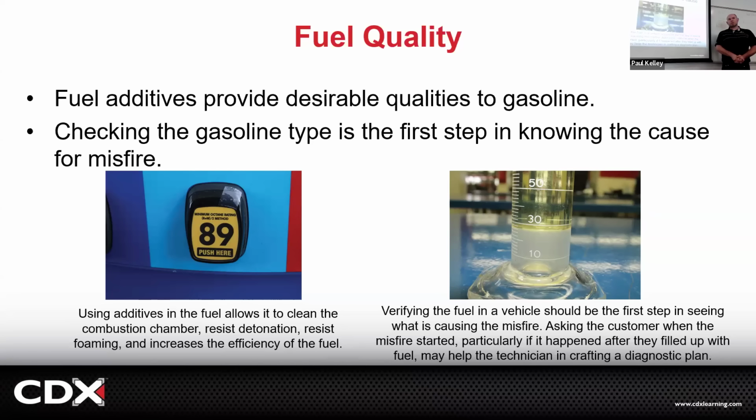I've seen it go for 6 months. I've even seen it approach a year. Anything after a year, that thing's gonna be messed up. So if you put fuel in something, a dirt bike, I've had this too many times, you don't use it for a year, and then you're like, "Oh, I finally got a day off, let me go start my bike." I got to clean the carburetor again. It just doesn't last that long. Fuel does not last that long. It's perishable. It expires. Okay, so everybody knows.